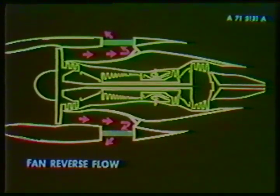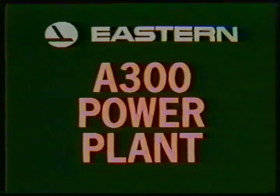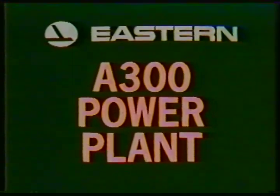Reverse thrust is applied by moving the reverse thrust levers upward, with the throttle levers remaining in the forward idle position. As soon as the reverse levers are unlocked, the ground spoilers extend if their control handle has not been armed. Part 2 will now show us the engine controls and indicators.